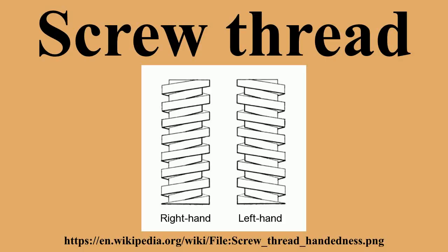Such allowances, or fundamental deviations, as ISO standards call them, are provided for in various degrees in corresponding classes of fit for ranges of thread sizes. At one extreme, no allowance is provided by class, but the maximum PD of the external thread is specified to be the same as the minimum PD of the internal thread, within specified tolerances, ensuring that the two can be assembled, with some looseness of fit still possible due to the margin of tolerance.